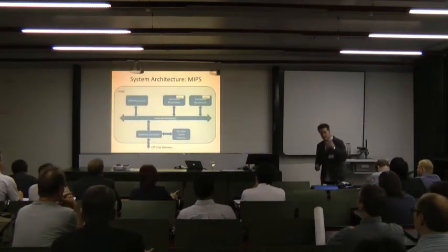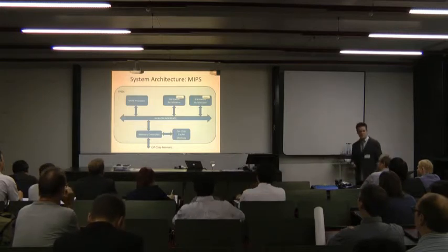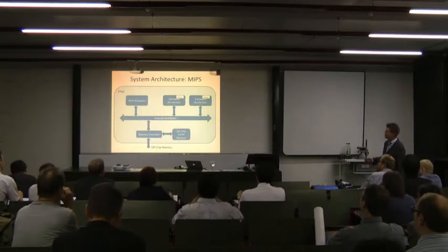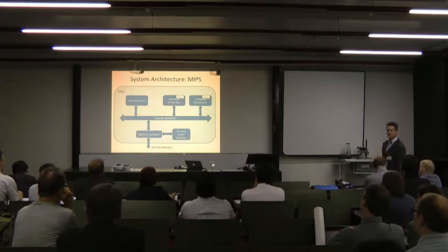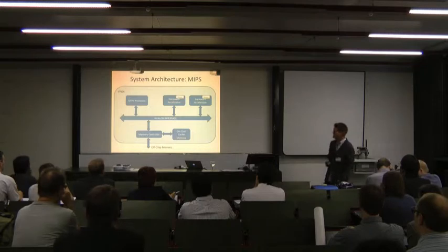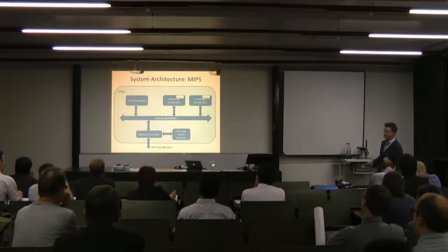Now, what does the architecture look like when you run LegUp? If you're using the MIPS computer, it's a software MIPS processor. You have the MIPS there on the northwest side, and 1 or more FPGA accelerators talk to the MIPS over a memory mapped bus interface. Don't worry if you've never heard of Avalon interface. Avalon interface, that's Altera's memory mapped bus interface. The computer and accelerators can share memory through an on-chip cache, and there's also off-chip memory.